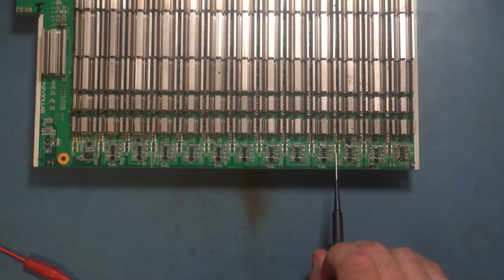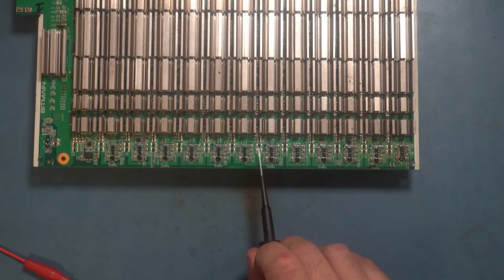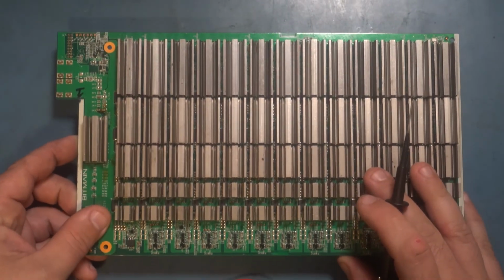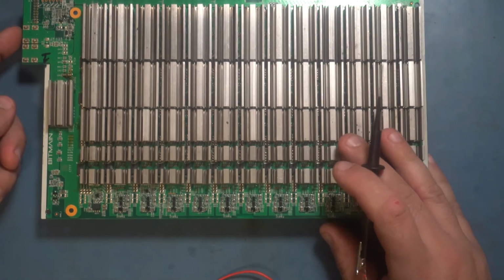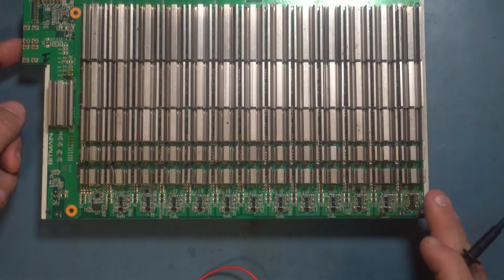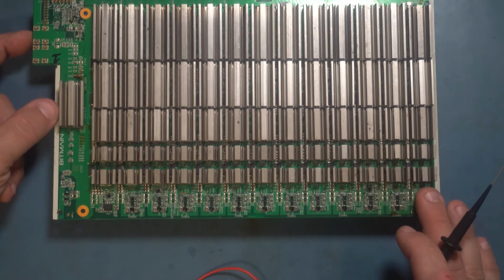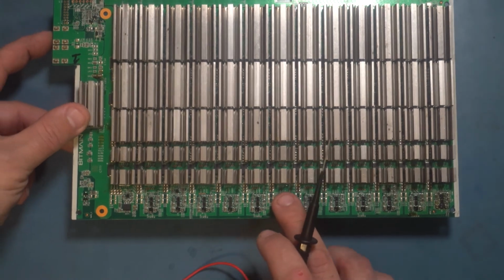But as we move up in domains, we know that the voltage increases in steps, right? So, talking about the voltage always relative to your main board negative. The ground of this domain is your main board ground, but as we go up, the ground of each domain goes up by 1.6 volts.